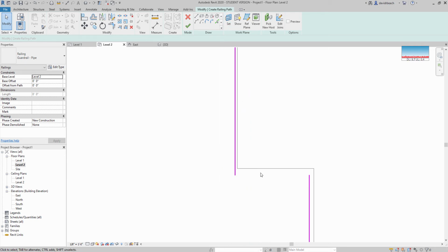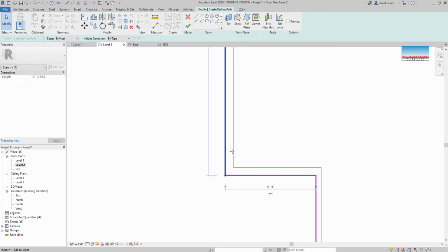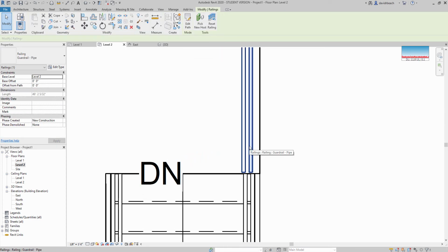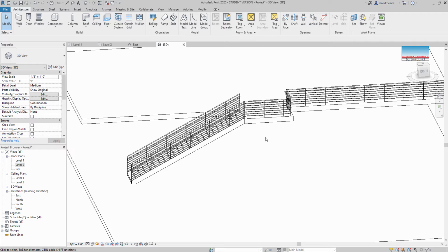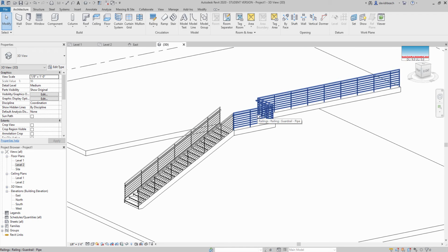Sometimes it's a lot easier to manage these pieces as individual components, right? Rather than trying to have these great big strings. And by the same token that I say that, let's nudge that over just so that starts to work. By the same token, as working with all of these elements, if I have a stair that's going to do a cutback, so in other words, it's going to come up and have a landing, a lot of times I would rather build that as 2 separate pieces rather than one continuous stair. So let's look at both of those pieces here as well.